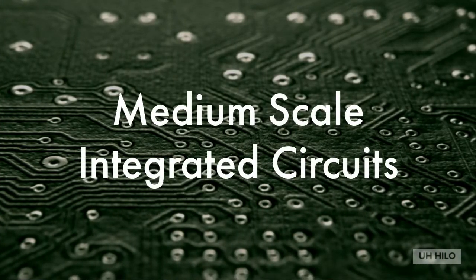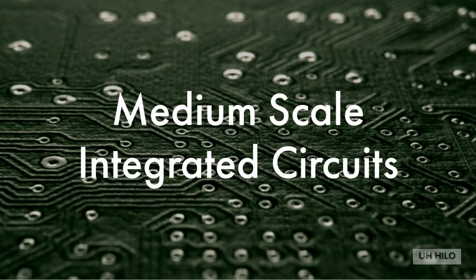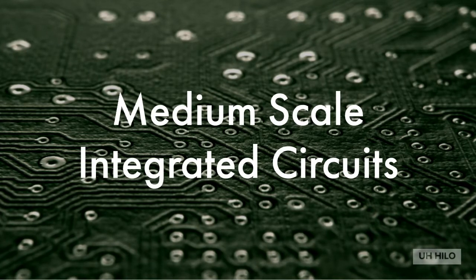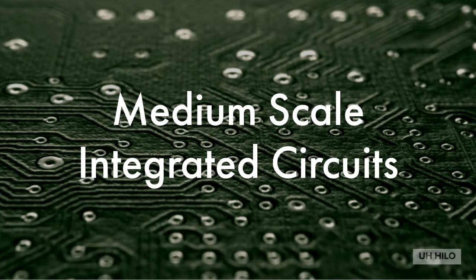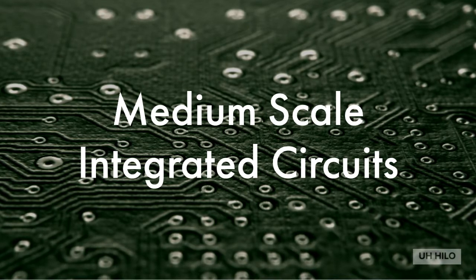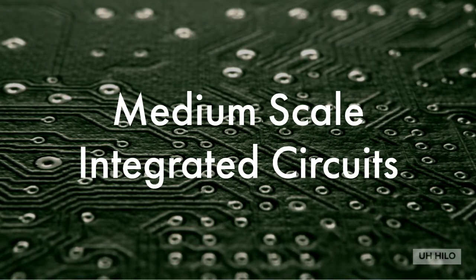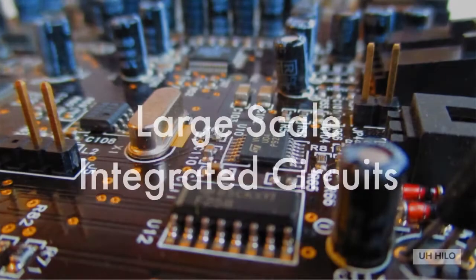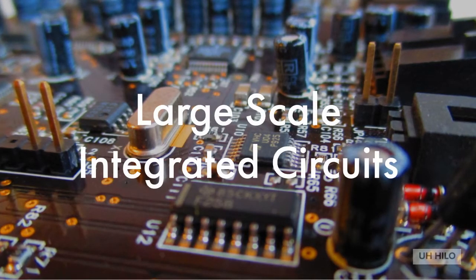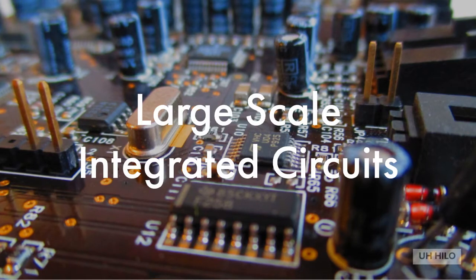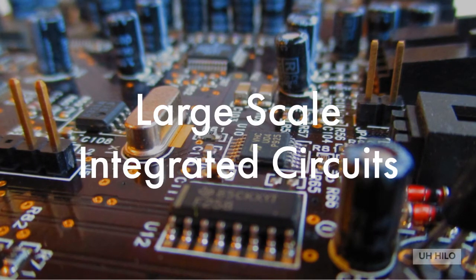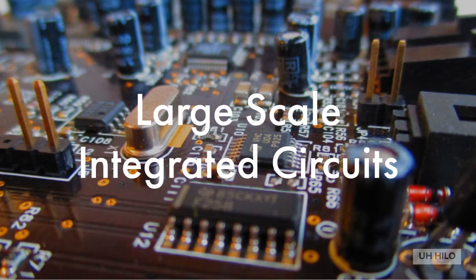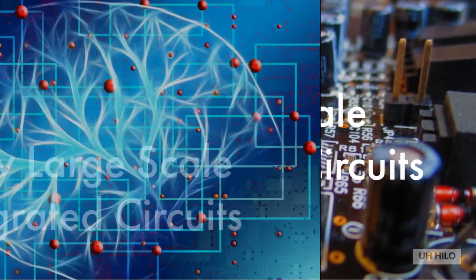Medium-scale integrated devices have approximately 10 to 100 gates in a single package. They usually perform specific elementary digital functions, such as the addition of 4 bits. MSI digital functions are similar to functional blocks that we talked about in Chapter 3. Large-scale integrated devices, LSI devices, contain between 100 and a few thousand gates in a single package. They include digital systems such as small processors, small memories, and programmable modules.